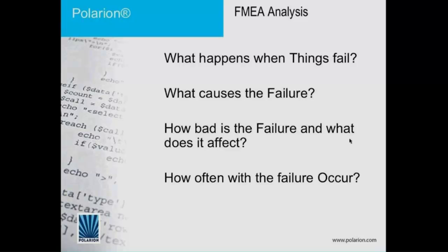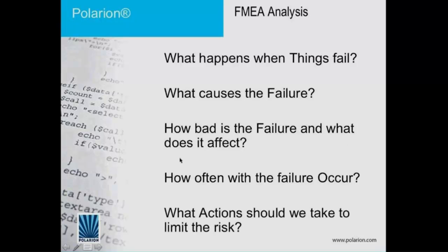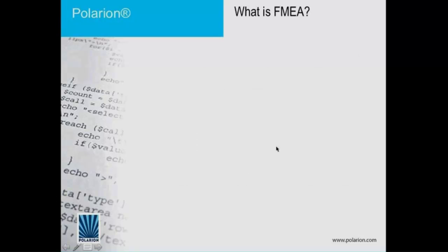But for other key products, such as medical devices or aerospace applications, failure can be very serious with respect to loss of human life. How often will this failure occur? And finally, what action should we take to limit the risk of the failure? All of these come together in a concept called FMEA, which stands for Failure Mode and Effects Analysis.